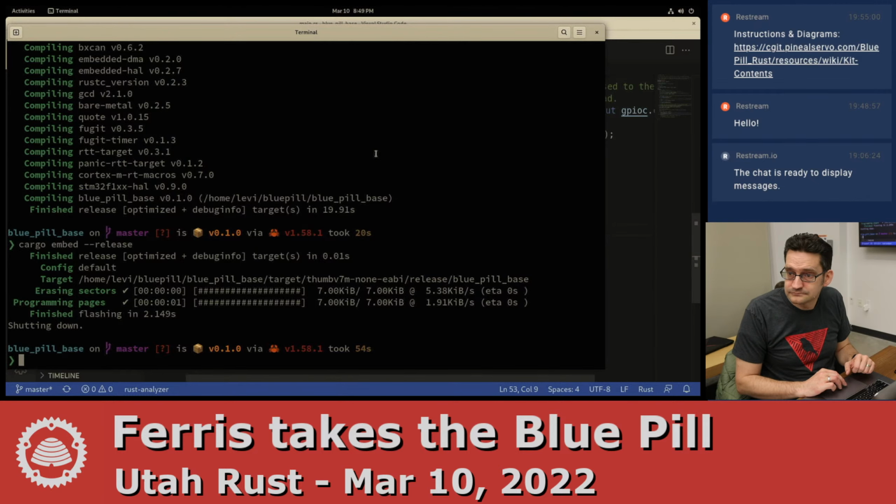So a question about panics. If you experience a hard fault in your Cortex-M, does that automatically invoke a panic? I am not sure what happens with hard faults. Generally those will trigger an internal condition, or whatever they call it, not an interrupt. And I think it probably hooks those up to a panic handler.